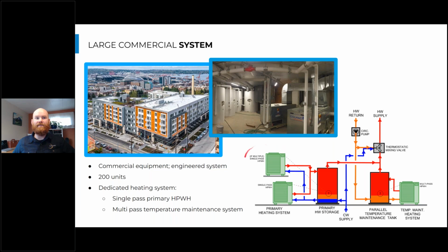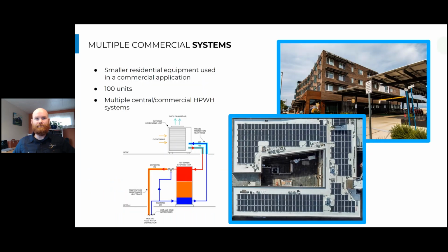These heat pump water heaters are heating cold water that comes in from the city and storing it to be used by the occupants. And it may be necessary to split out those two use types, or those 2 loads. And the Seattle Energy Code actually requires that in some situations, which we'll get into later.